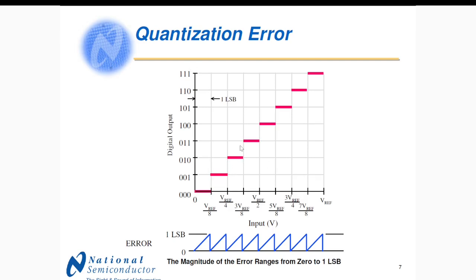These are the steps, and as we mentioned here, we are not capturing the signal, which is potentially constantly changing. So these steps are primarily called quantization error. It is one least significant bit, and since we are constant in that particular window, it has 1 LSB of quantization error, and that's what this particular slide means.